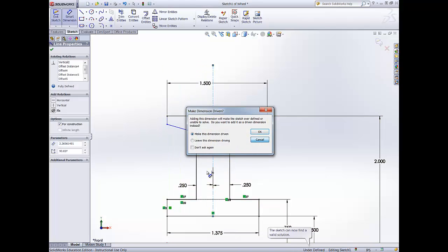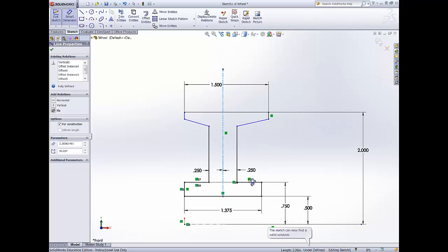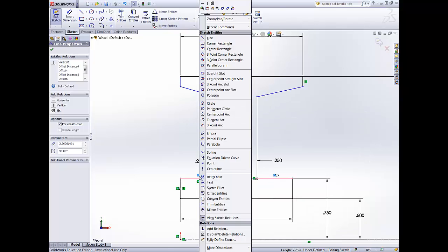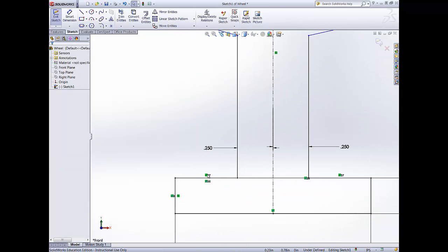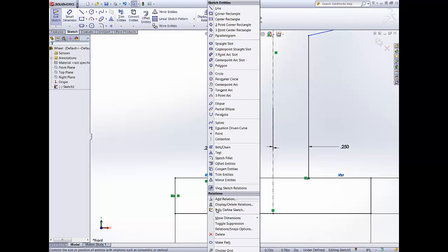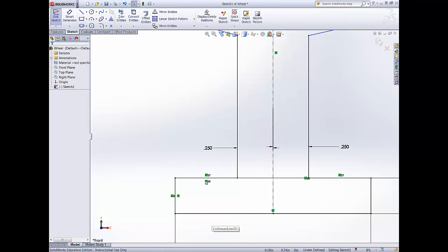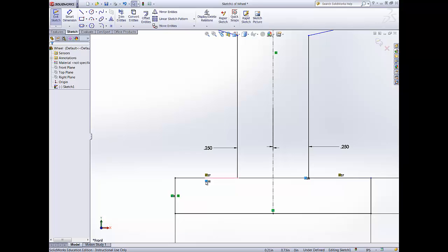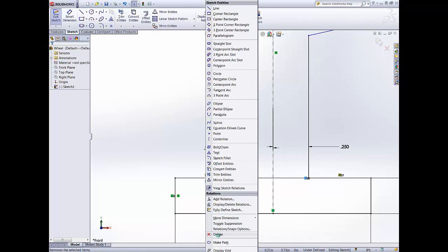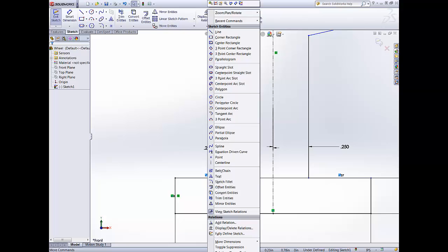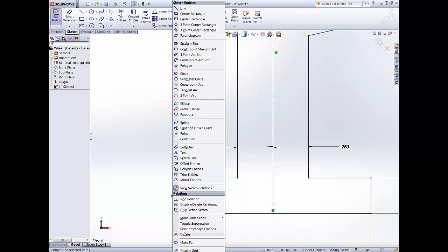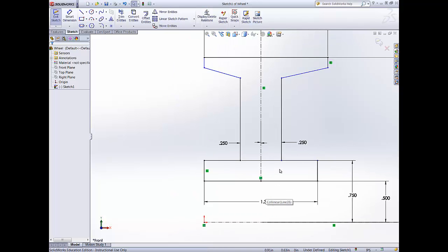Gotta get it constrained. So I'm going to go ahead and take off these constraints because they're pulling us back just a little bit. So these are made equal. So what I'm going to do is just delete those out. And again, your drawing should be working fine. I just want to show you the edits that need to take place. And we're taking these out so we can do the modifying that we need to. And we can always put them back in as that happens.